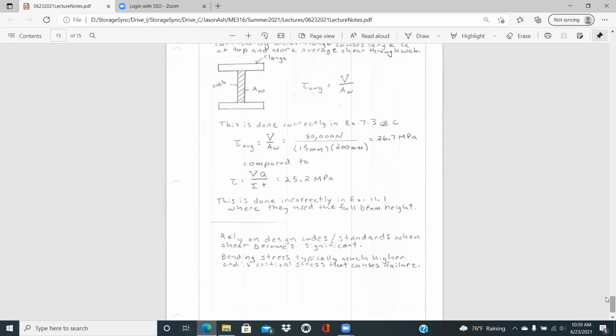And so as we continue on into the week, on Friday, we'll be discussing the transverse shear stress in built-up beams. When you fasten things together with fasteners or nails, those fasteners would have to carry that transverse shear load. And so you want to make sure to identify the spacing of the fastener so that it can adequately support that transverse shear. And that'll finish us out for chapter 7 on Friday.